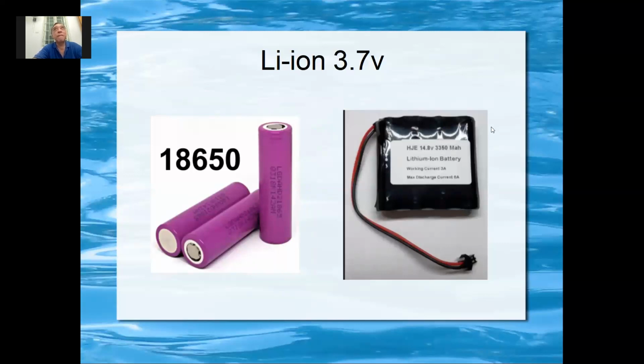But it's just a dimension. Most of the time it is replaceable. You can use either lithium ion or lithium iron. The full name is lithium iron phosphate, and the difference is 3.7 and 3.2 volt. So a lot of devices will be able to absorb that small difference in voltage.